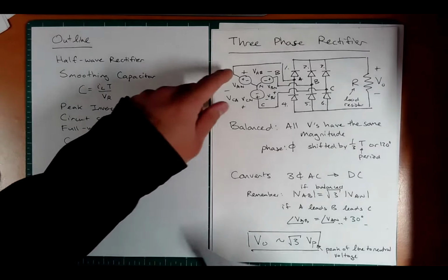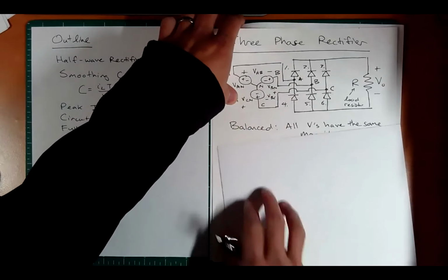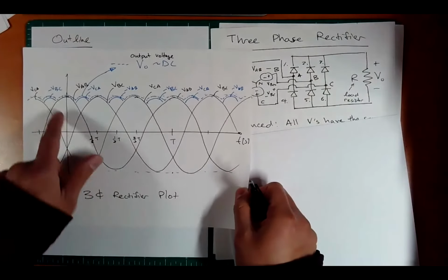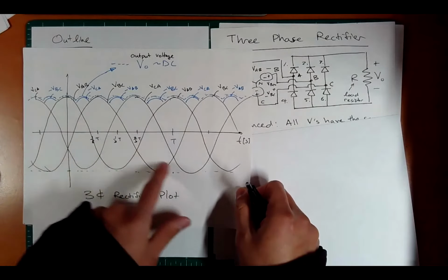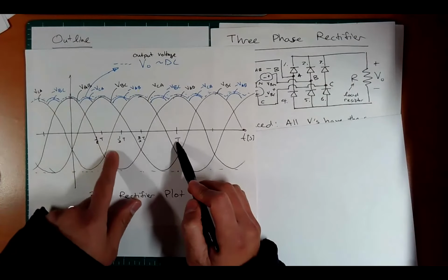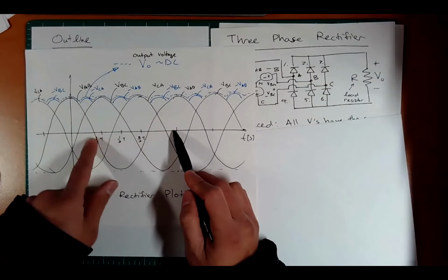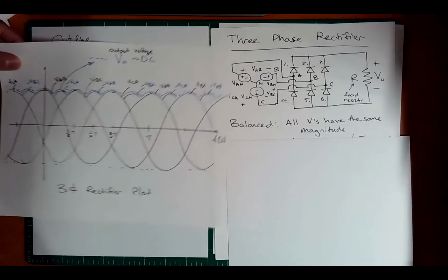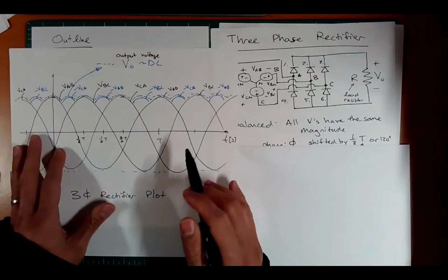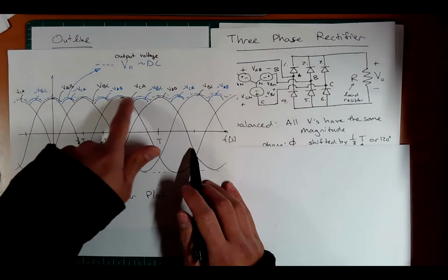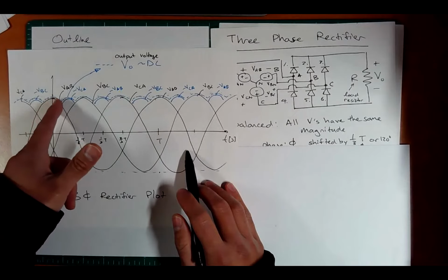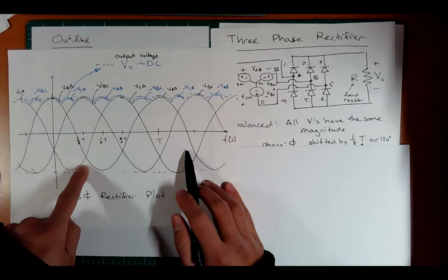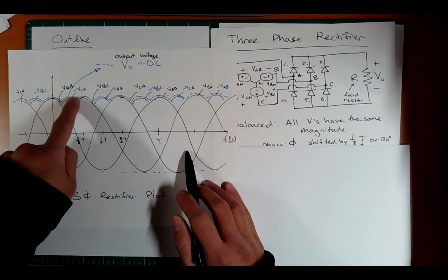Okay, so let's plot the line-to-line voltages on a time waveform where the x-axis is time and the y-axis is the amplitude. So notice I have the three-phase AB, BC, CA, offset by 1/3 and 2/3 of a cycle in one period. So at 1/3 period, you can see the BC is lagging. The other thing I want you to note is that I have drawn the maximum peaks right here on the top. So for example, in this time interval, VAB is positive and maximum, but here VCA is negative and maximum. But I flipped it, I put the negative VCA up here.